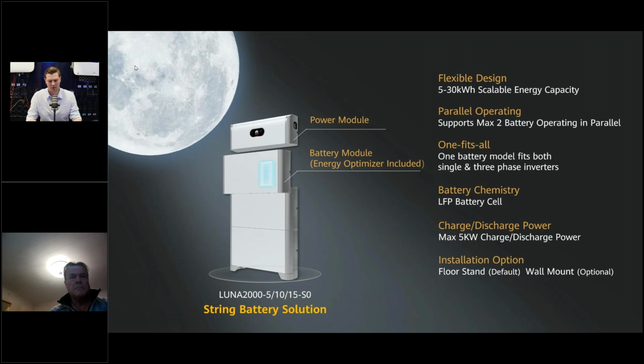So this is quite safe technology. And secondly, what's behind that safety: even if the situation happens and we exceed the runaway temperature, which in our case is 480 degrees, the chemical reaction behind the burning process does not generate oxygen as a part of the reaction. So the battery will produce a lot of smoke and of course burn out the material inside, but there will be no oxygen causing an actual explosion of the battery.